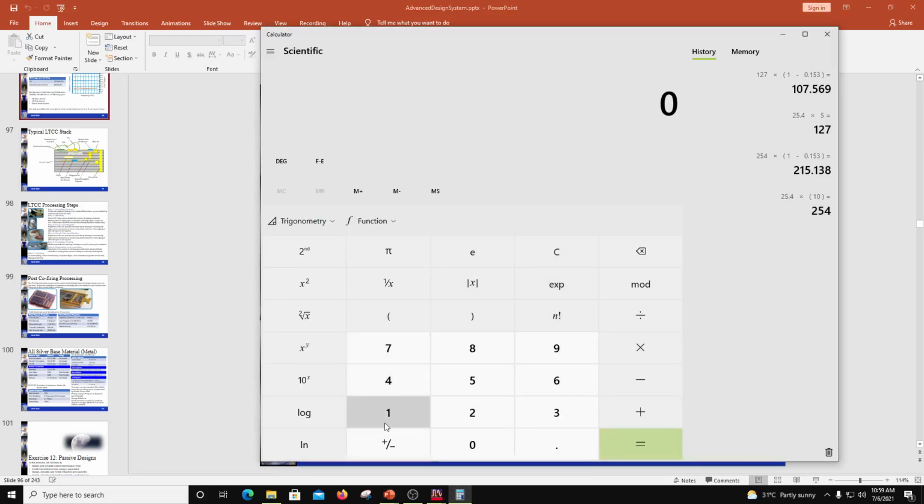Clear this. So you have got 25.4 multiplied by 5, and then this has to be multiplied by 1 minus 0.24, bracket close, and that's it. So it should be 97 micron for 5 mil substrate. Post firing the thickness will shrink down to 97 micron for 5 mil.